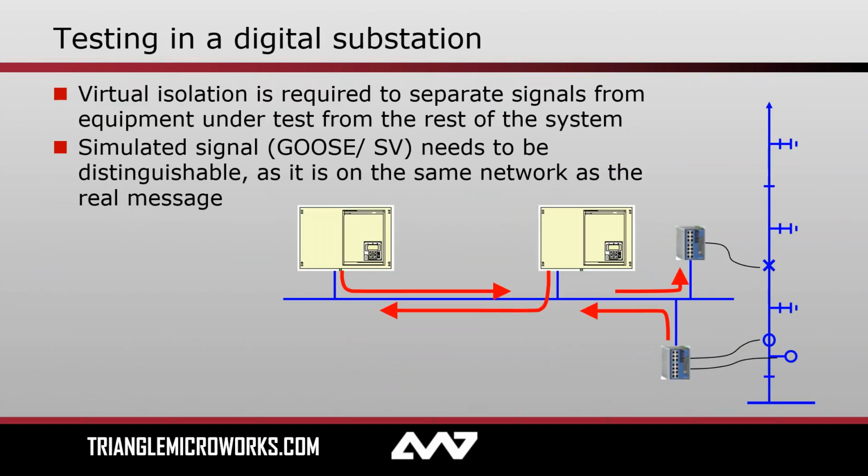So in the digital substation world, depicted here in this diagram, we can see our IEDs on the right-hand side. These might be merging units or process interface units, PIUs, which are connected to our CTs and PTs and passing information via process bus, so sample values, also GOOSE as well, to different IEDs, which might be making decisions based on that information.